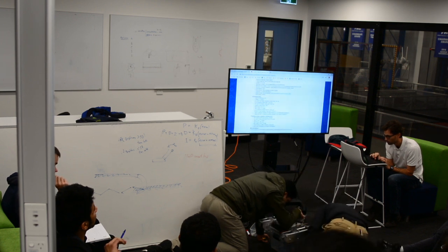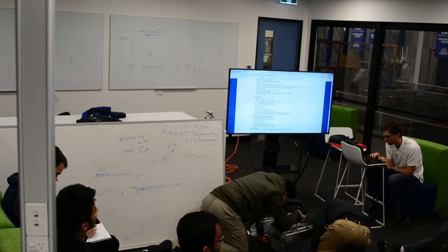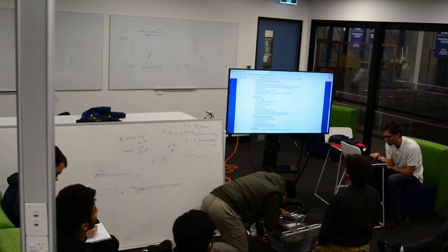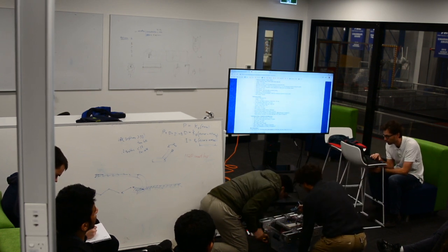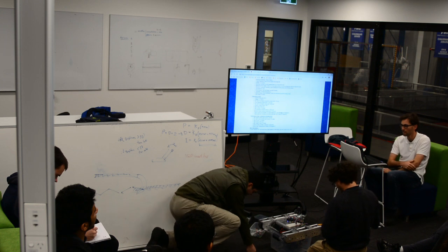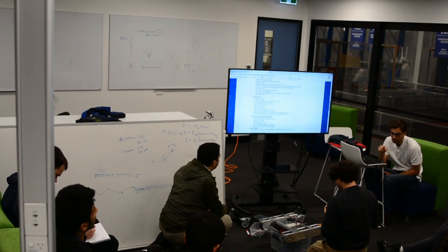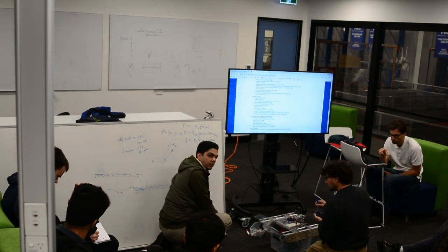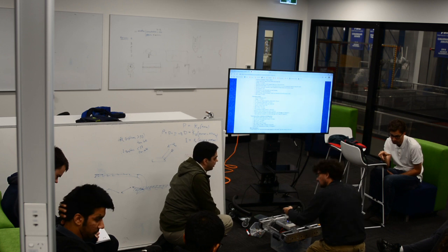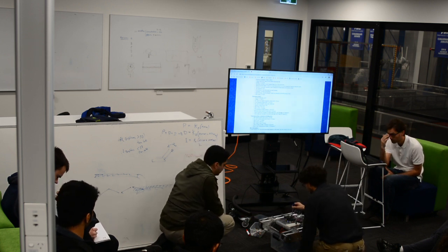Here we go, yeah. Output counts per revolution of output shaft: 1120. 280 rises of A. Okay, so that's the total number of pulses. So I would guess we have 280 pulses on A per revolution. I think that's directly coupled. So we were doing 1,000, which should be about 3.5 rotations of that wheel. That's about right, it seems, for the distance we were going.